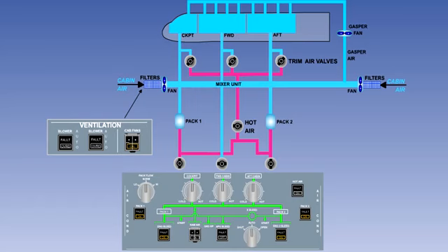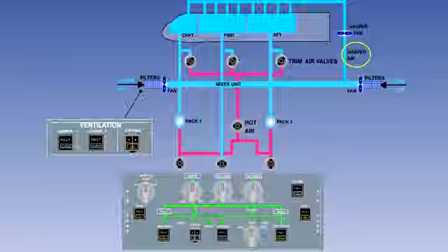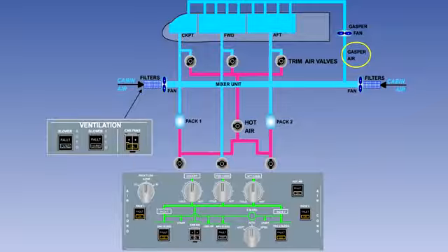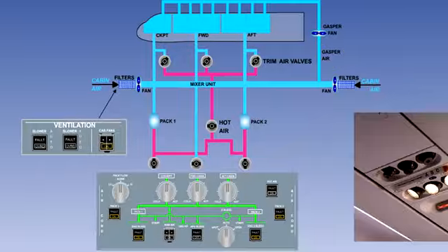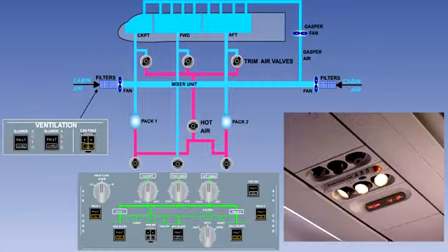The ducting is in 2 distinct sections, to provide for separate flows of cold and heated air. The cold conditioned air is supplied to the passengers individually, through a system known as the Gasper air system. Gasper air is tapped from one of the zone's supply ducts upstream of where trim air is added. The Gasper fan provides a positive supply of conditioned air to all zones through individually controlled outlets or punker louvers.